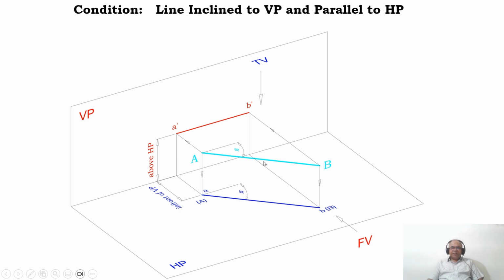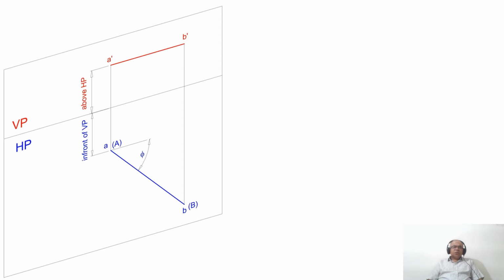See, this is in 3 dimensions which you have been able to understand easily. But how to represent that in your 2 dimension orthographic view? So what I am doing is I am rotating the horizontal plane by an angle of 90 degrees. Once you rotate by the angle of 90 degrees, then the corresponding images also get rotated. So here the same thing has been copied. Now this is the front view and this is the top view.